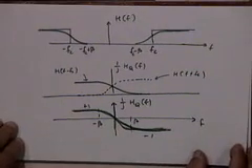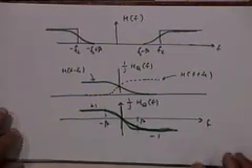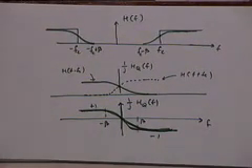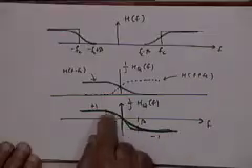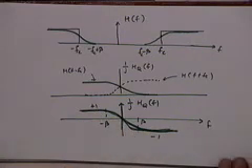I will just prove to you that for the case of SSB, this theory that I have developed is consistent with what we discussed earlier. That's all I said. Whatever theory we have developed for the general sideband filtering is consistent with what we have learned for the case of SSB signal, because this filter HQF then reduces to the Hilbert transformer. But in general, it is this kind of a filter, which is not a Hilbert transformer.